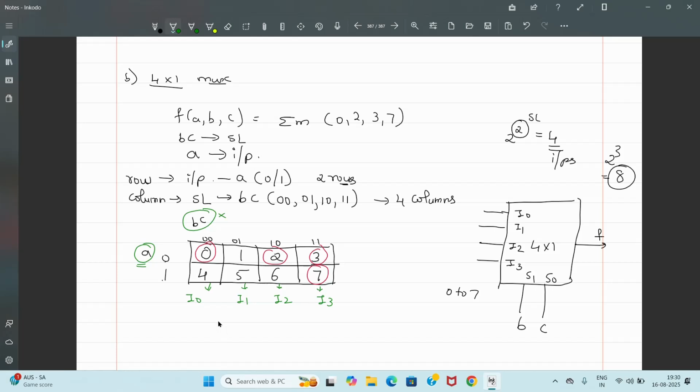So how do we write the input? Two things. If both the cells of that column are covered, then your answer will be 1. If none of the cells of the column are covered, then the answer is 0. If only one of them is covered, the corresponding variable should be written in the output.